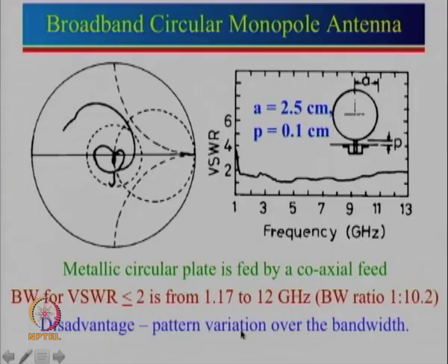In fact, we did many other experiments also. We had this monopole antenna, and we even put a reflector here, just as I said. So there is a ground plane and a reflector, we kept on changing the dimension, and we could get more gain in this particular direction also. Many different things were studied at that time. So one can see that this circular monopole antenna can be explained very conveniently using the concept of the microstrip antenna.